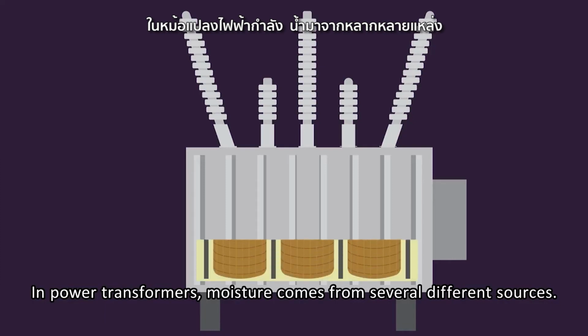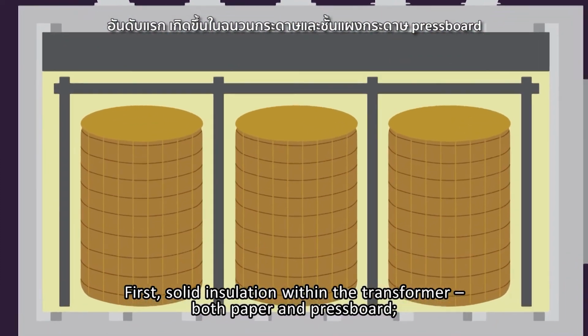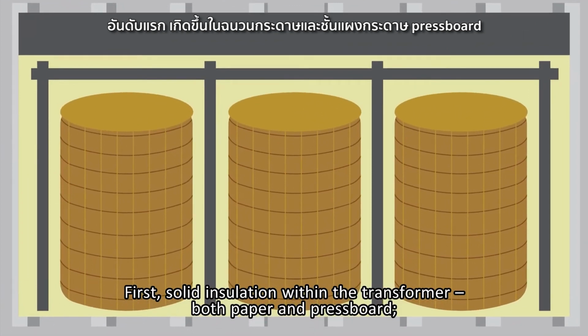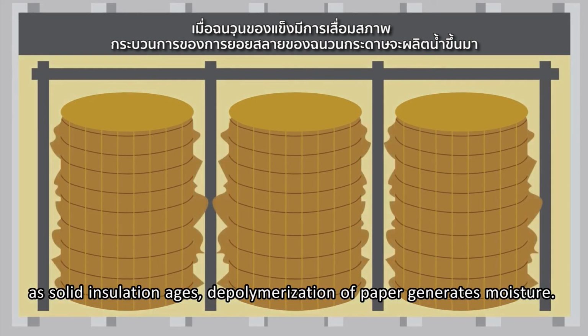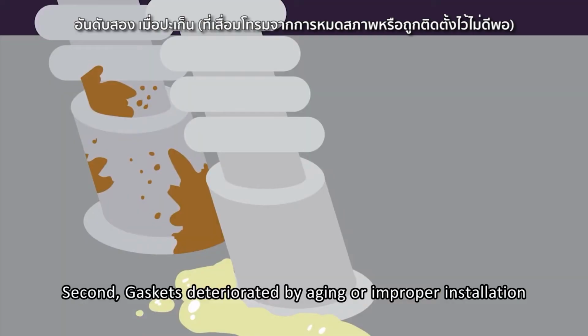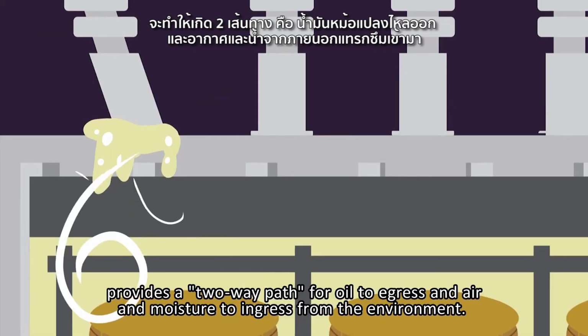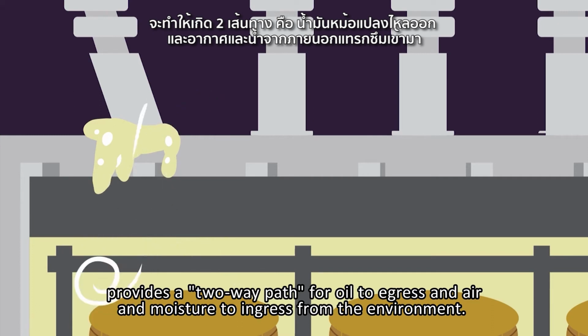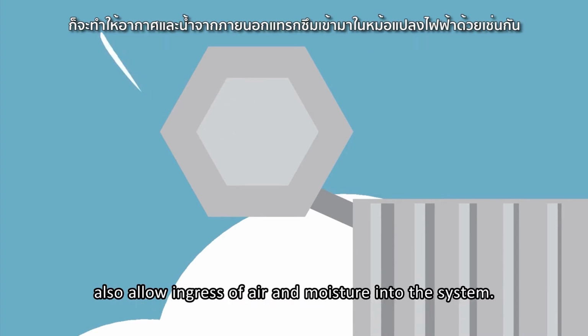In power transformers, moisture comes from several different sources. First, solid insulation within the transformer, both paper and pressboard. As solid insulation ages, depolymerization of paper generates moisture. Second, gaskets deteriorated by aging or improper installation provide a two-way path for oil to egress and for air and moisture to ingress from the environment. Finally, broken conservator bags and non-functioning nitrogen gas blanket systems also allow ingress of air and moisture into the system.